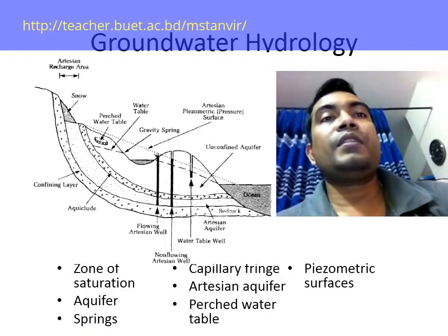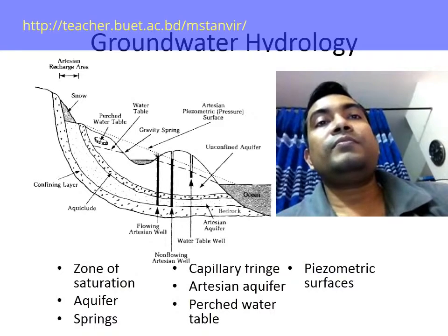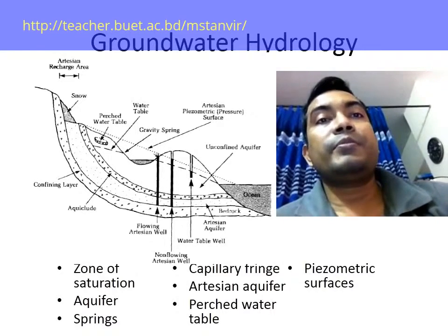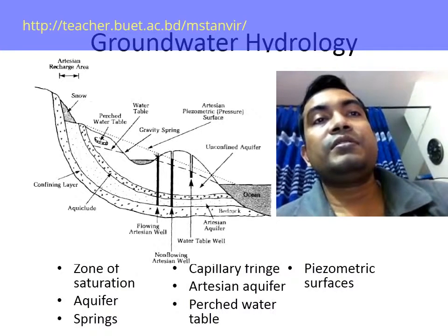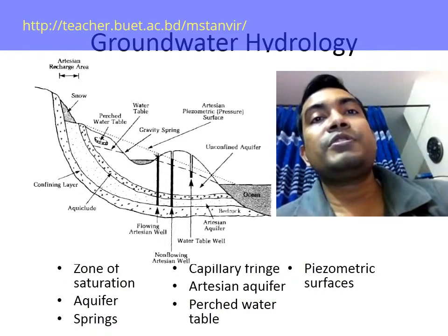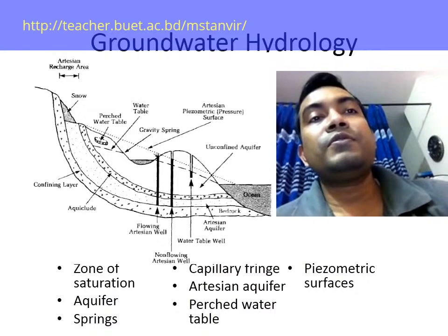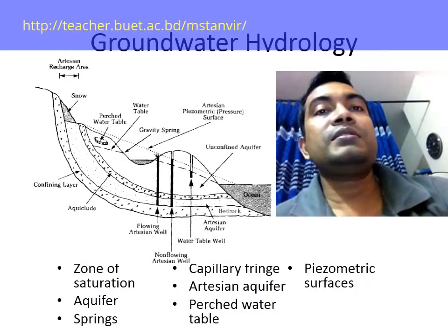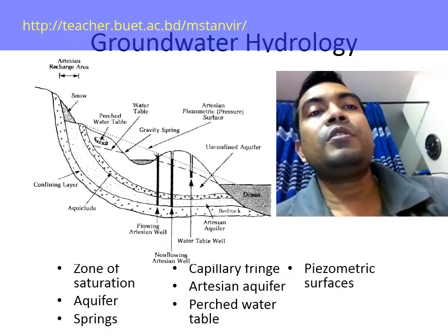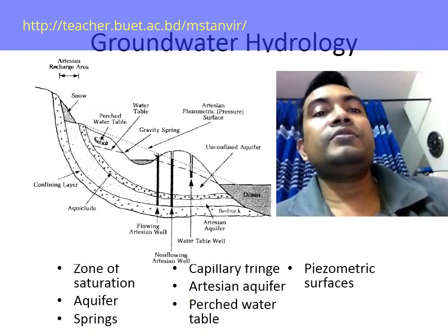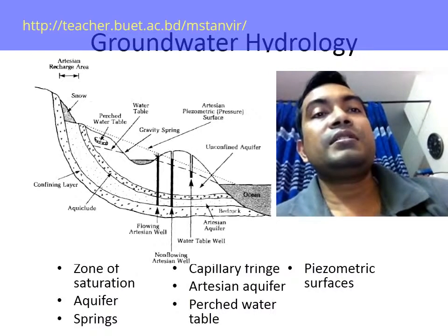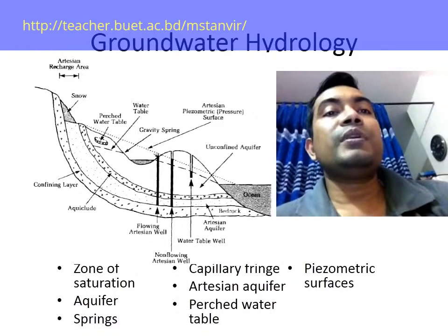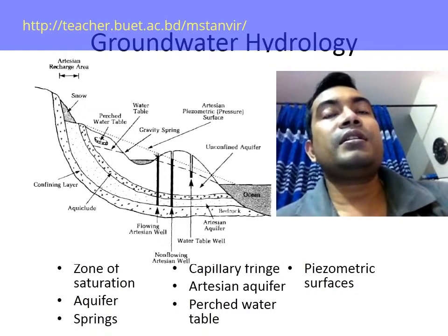Artesian well. Water in the zone of saturation under a pressure greater than atmospheric that penetrates artesian formations flows above the surface of the land. The water in the well must stand above the top of the aquifer. The recharge area must be at an elevation higher than the bottom of the aquifer to make the aquifer artesian.